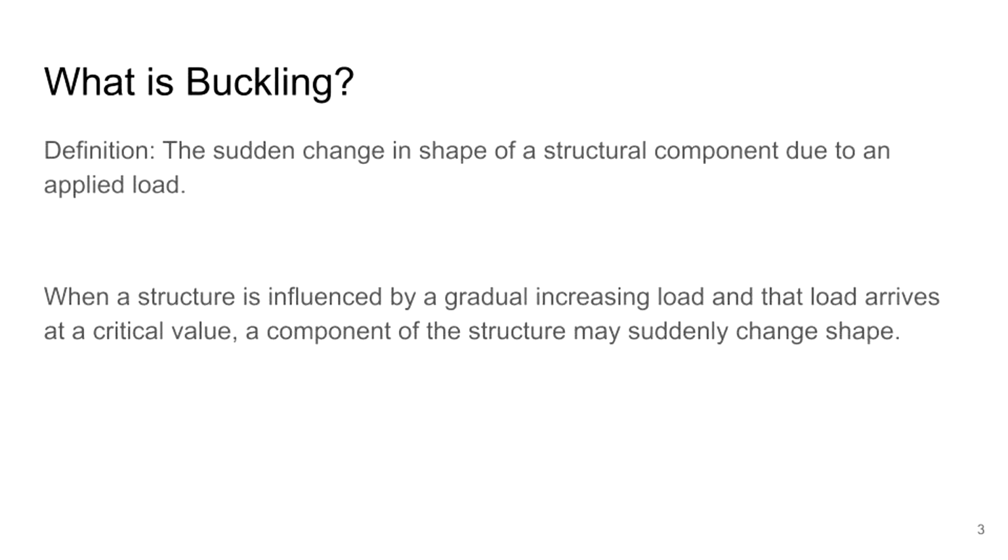Buckling may occur even though the stresses that develop in the structure are well below those needed to cause failure in the material of which the structure is composed. Further loading may cause significant and somewhat unpredictable deformations, possibly even leading to complete loss of the member's load-carrying capacity. However, if the deformations that occur after buckling do not cause the complete collapse of that member, the member will continue to support the load that caused it to buckle.